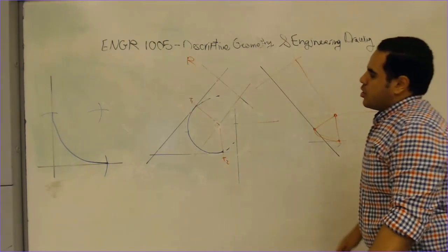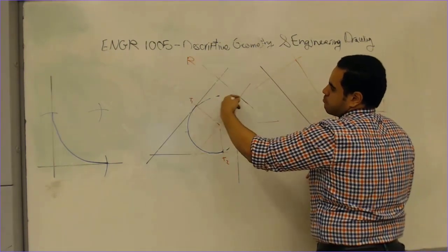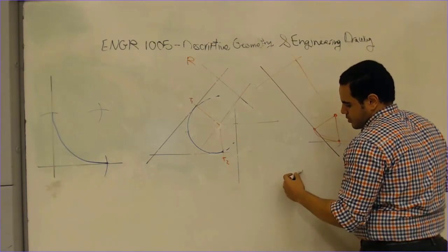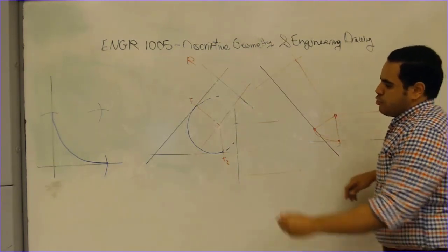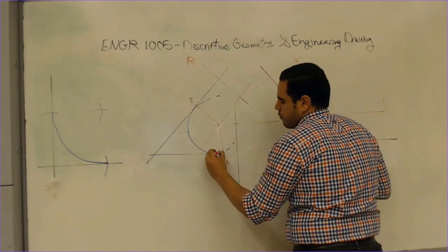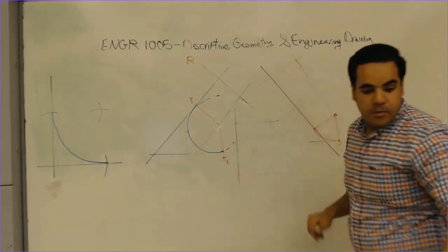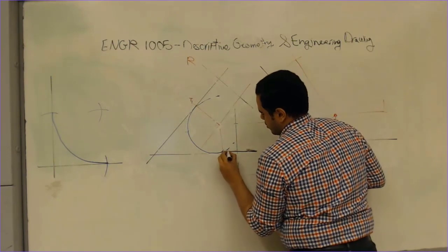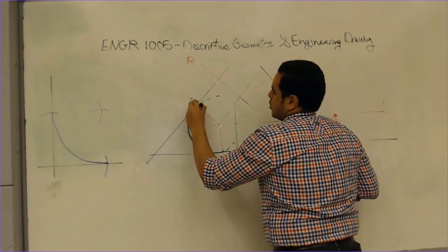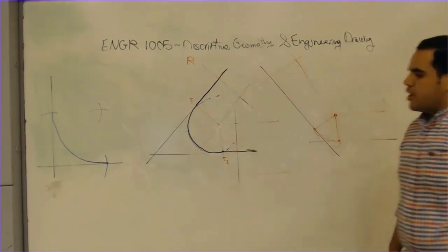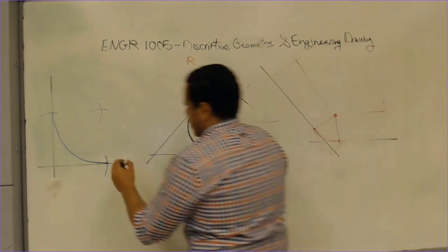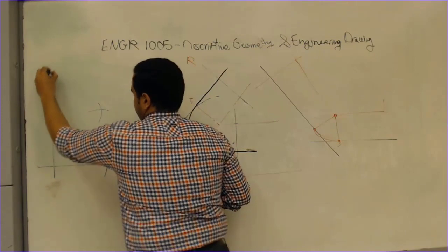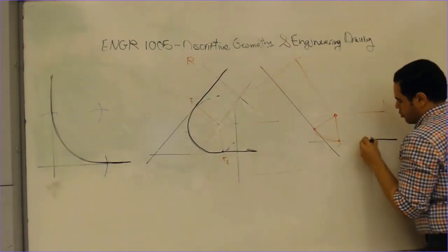So all these marks and parallel lines and notches are just construction lines. You draw them with a slight touch of your pencil. But we want you to push a little for the object lines, which are these: the given lines, your solution, and the other one. Any other thing is going to be with a light font, okay? So this is our answer, and here, this is your answer.